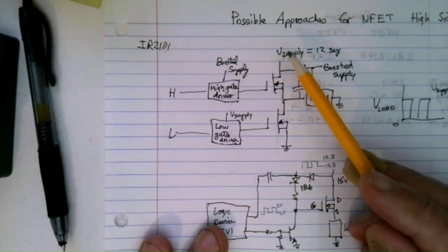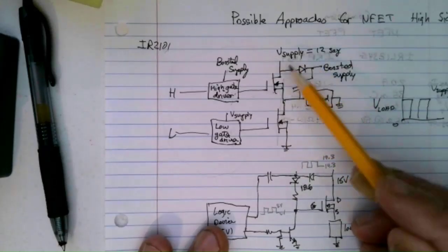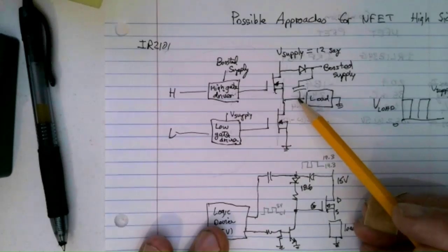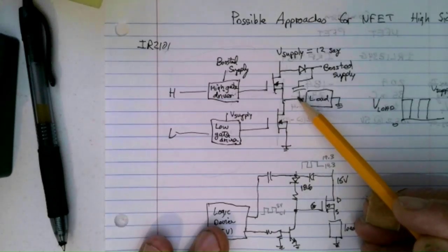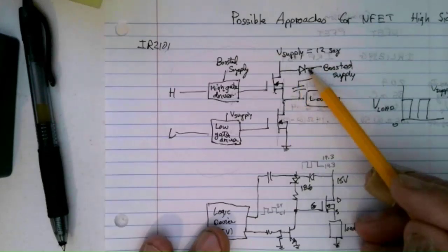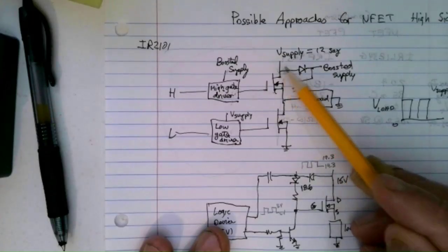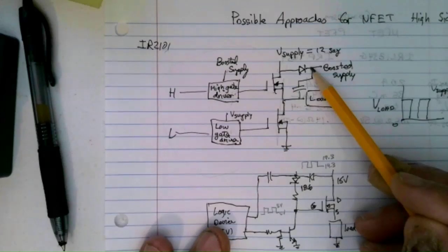And so what this circuit does, I'll tell you in words, is that it takes the AC here, because presumably this is some kind of PWM application, motor driver speed control or whatever, and this is toggling, so there's AC here, and this capacitor samples that AC, and this diode half-wave rectifies it. But you notice this diode is connected not to ground, but to the 12-volt supply. So this voltage will be higher than 12 volts here.